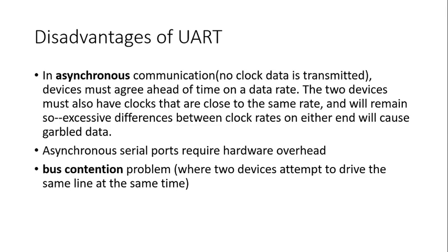The second part about asynchronous communication is that asynchronous serial ports require hardware overhead. It means they require complicated hardware to perform that, adding the start bit, stop bit, and parity bit. So it requires hardware overhead.